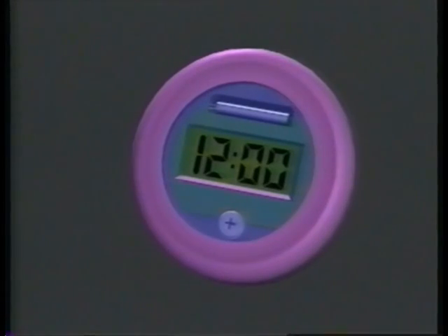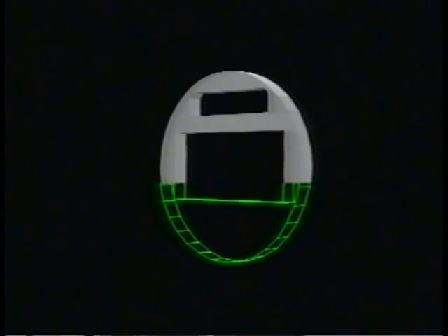To build a model of the digital watch, complete with display, case, and circuit board, we'll start with a circle. From this initial polygon, we can extrude a three-dimensional disc. After joining the faces of the disc, we can punch two rectangular holes through it to create the base of our watch. Shrinking down the same rectangle we used for one of the holes, we can create the block for our display. Next, we'll bring the face of this block to the screen and draw in the shapes which make up one of the digits.